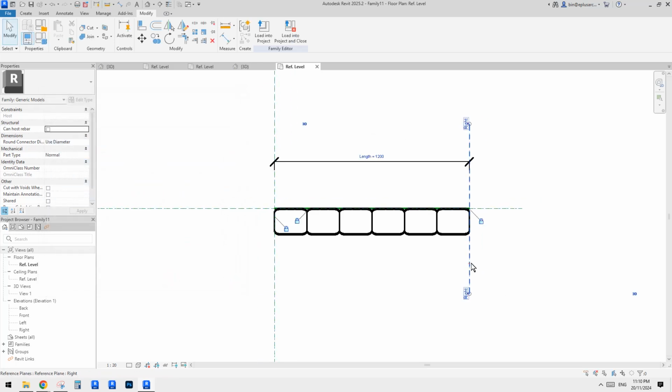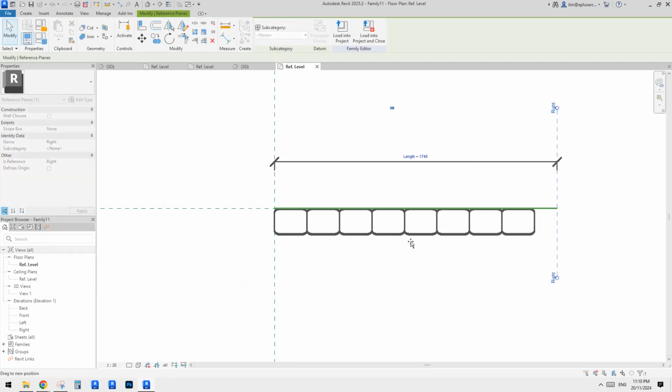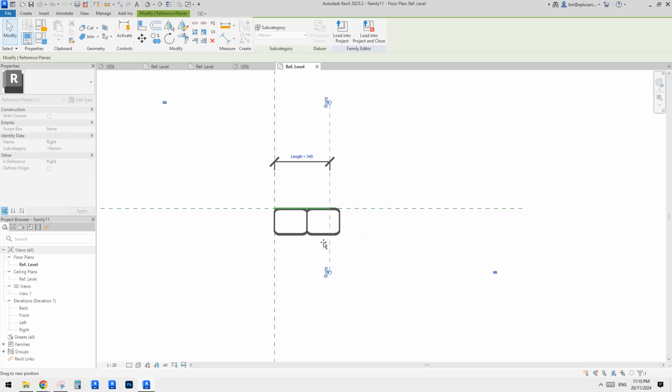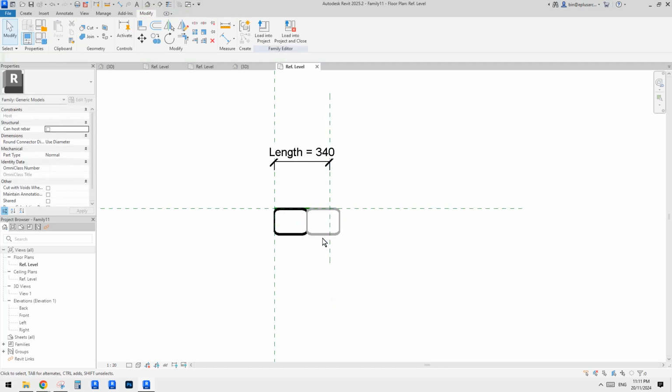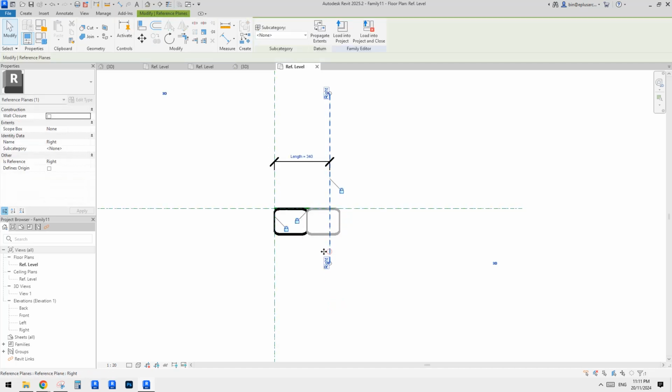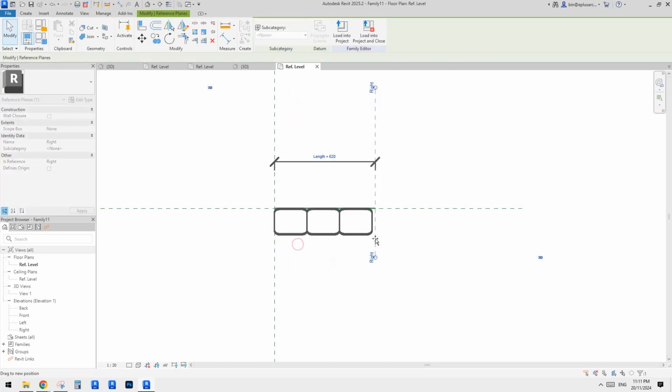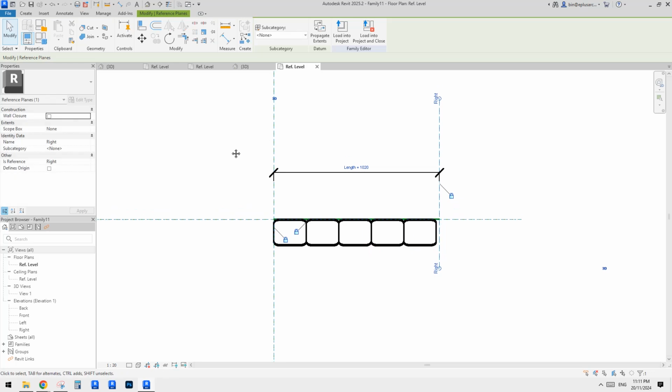Okay, so now if you change this one, it will automatically change the number. And also once again, the good thing about 2025 is when we reduce this array number to smaller than 2 for number 1, it will automatically hide the second one. And if you reduce even more, when the array becomes 0, it will hide both. Okay, so we don't need to create an 'if number smaller than 2 equals 2' formula, something like that, anymore. Okay, so yeah, which is good.